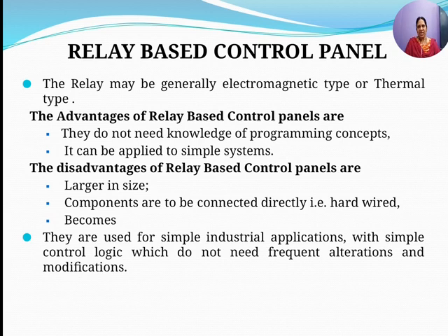When the sensor senses an object, it makes current pass from the power supply to the coil, by which the coil gets energized and turns the NO contact on. The NO contact closes the circuit of the power supply to the motor, and the motor begins to run. So here no programming technique is used. They do not need knowledge of programming concepts.